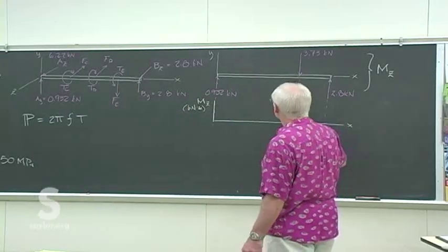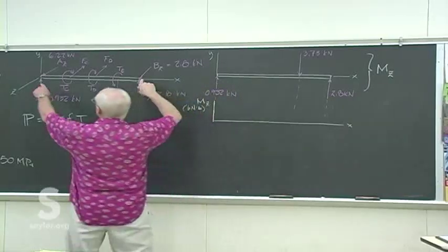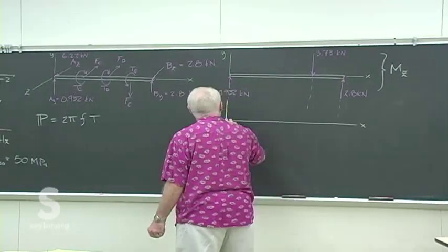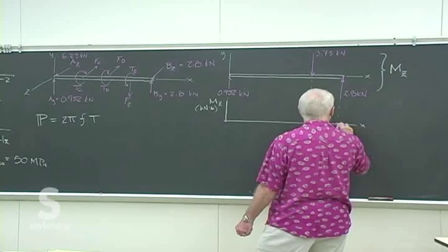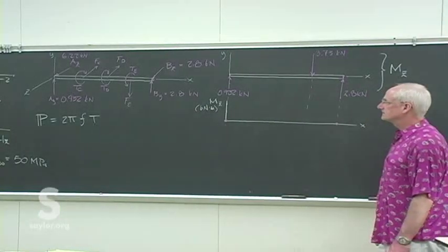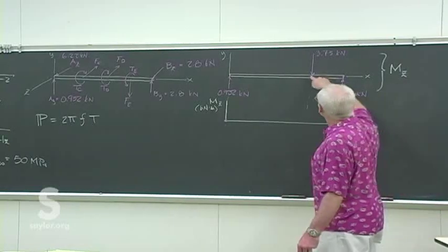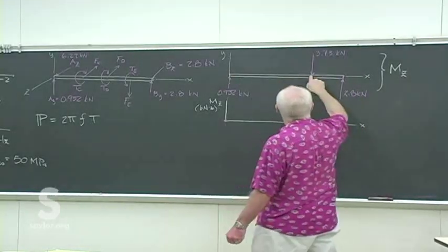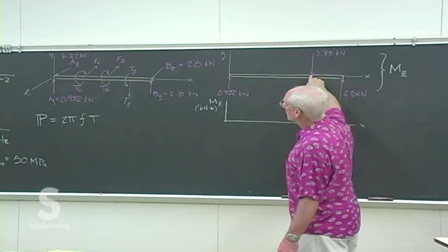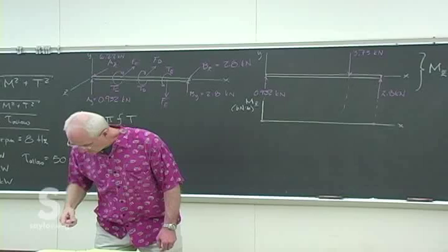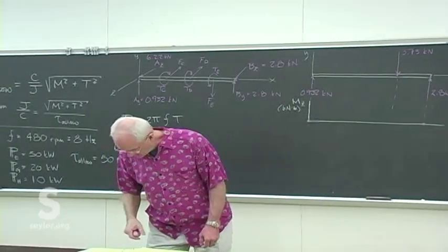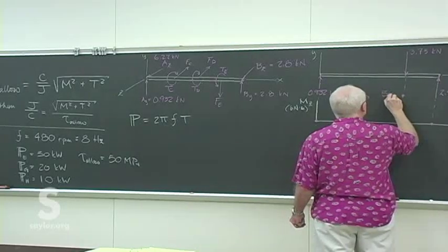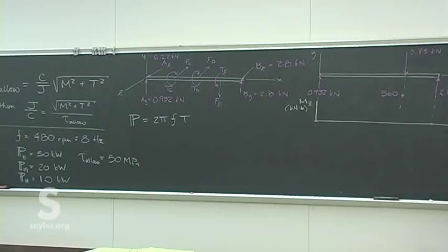So let's see. Because the two ends are simply supported with just journal bearings that can maintain no significant moment, we know that the two end moments are 0. And the only place we have any transverse force being applied is 3.73 kilonewtons, and that will have a moment arm all the way down of what was it, 20.6 or something? I think when we got there. So we'll have then a maximum expected moment there of 560.